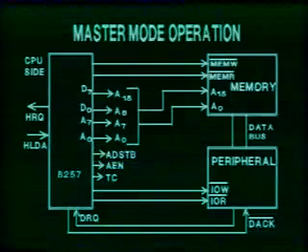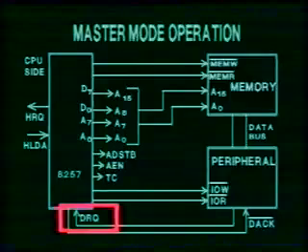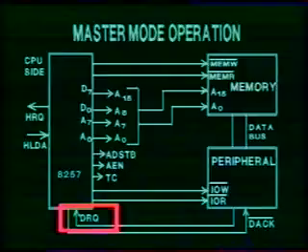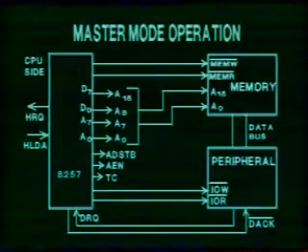Another important aspect to be noted when the DMA controller works in master mode is that the DMA request from a particular channel should remain high if it requires block transfer as long as the terminal count becomes 0. If on the other hand the DMA request becomes inactive when the acknowledge is given to the channel, the transfer will stop with a single byte of information.